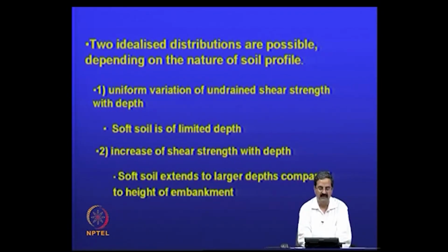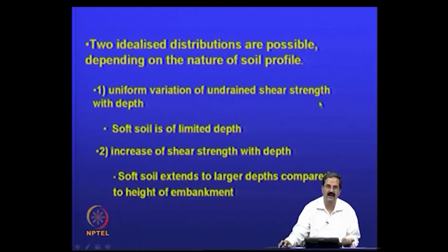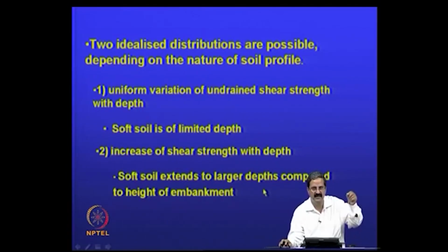Again, one can get the information from the cone penetration test, and if the soft soil extends to deeper depths, you had better consider that shear strength increases with increase in depth. The shear strength value will be higher at a deeper depth than for a sample at a shallow depth.